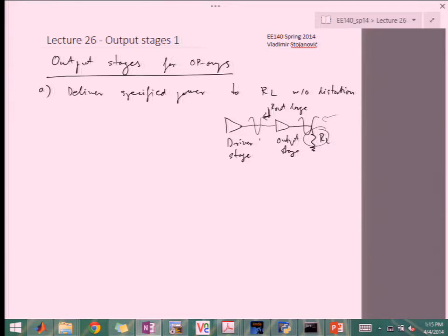Okay. Under B, in order for this voltage Vi to be most faithfully copied to the output VO, in the situation where we have these different impedances, we want this driver to really act as a voltage-controlled voltage source, meaning that its output impedance is very low. So it's really unaffected by RL.